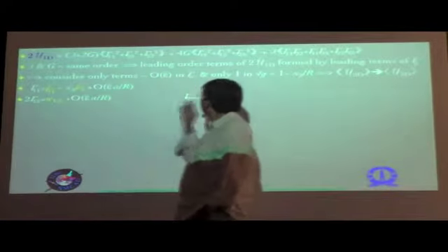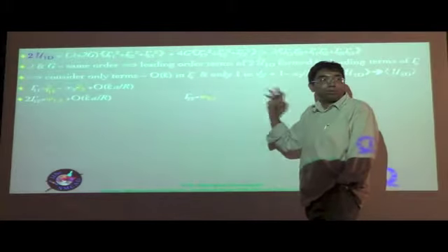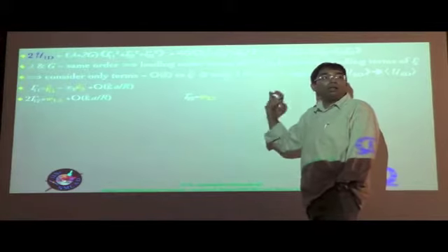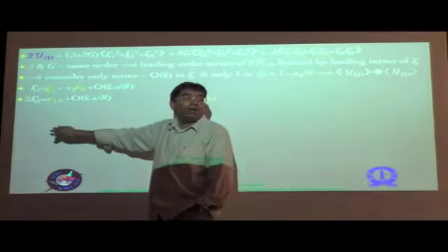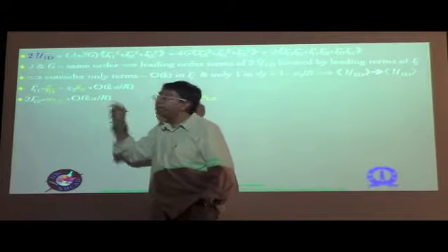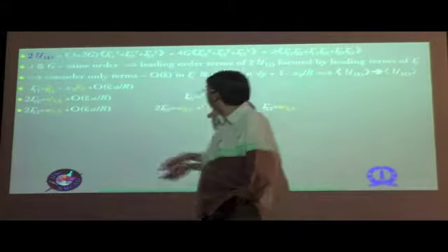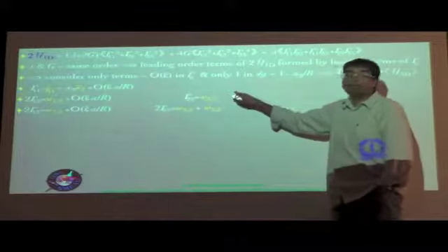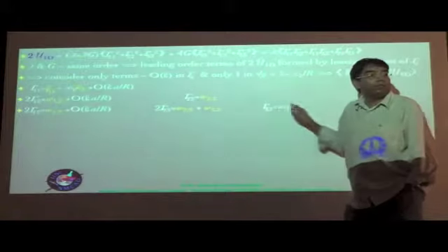Next, we have these terms 2 gamma 1 2 and gamma 2 2. As far as the gamma alpha beta terms are concerned, they are all as they are, the exact expressions, because they are very simple expressions and they all have terms which are of the order of epsilon hat, so they remain. It's only in the gamma 1i terms, that is those three terms, that you will see this difference. And so here only w1 comma 2 is there, the rest are higher order terms. Similarly here only w1 comma 3 is there, the rest are higher order terms. Here we are not even adding plus order of something, because this is the exact expression already. We don't have any more terms in these three strain measure examples.